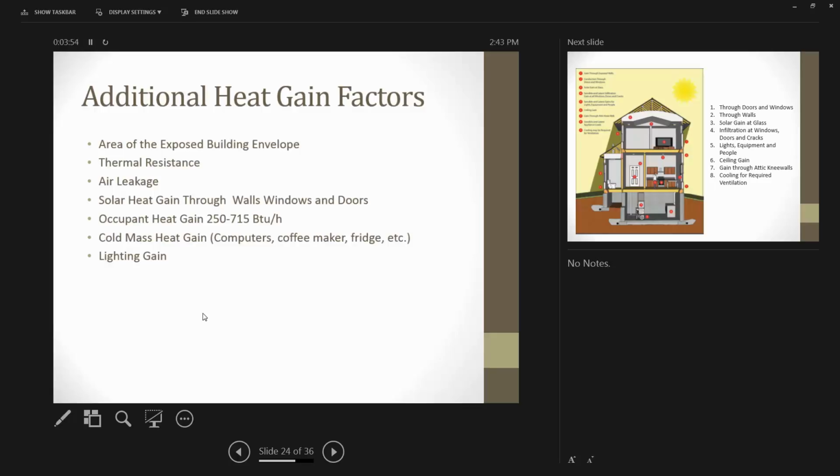The other thing we talked about in lighting gain, I think last week, was the one building that I mentioned. They got excited about energy efficiency measures, and they were going to save a bunch of money by putting in CFLs, and actually did use that very spreadsheet that I showed you earlier on what was going to be more cost effective, and they replaced I don't know how many hundreds of CFLs, and they realized that the money they saved on their CFLs they lost because the incandescent bulbs were contributing so much to their heat gain. They were actually keeping it warmer in the wintertime.